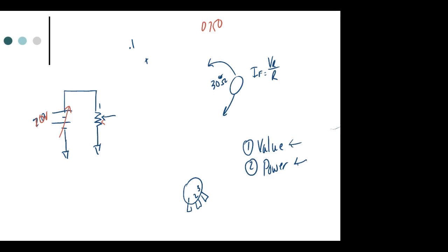Does that make sense? What's very important is you take one of the leads that is not the wiper and connect it to your common. This will be common. This one right here is going to go back to the V plus output of the trainer. Everybody understand that? Then the wiper, this guy right here, is going to come over here and feed the resistor. They have the resistor first in the circuit. And then our diode is going to be right there.